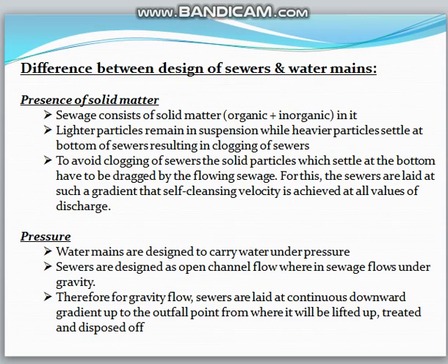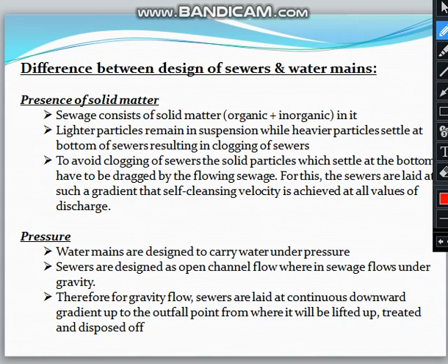Next, before we go on to discuss the hydraulic formulas for design of sewers, there is a term called self-cleaning velocity. The self-cleaning velocity is the velocity which causes both floating and heavy solids to get transported easily. It may be noted that the larger the size of the sewer, the higher is the velocity of flow. That means a larger sewer pipe diameter gives a higher velocity of flow.